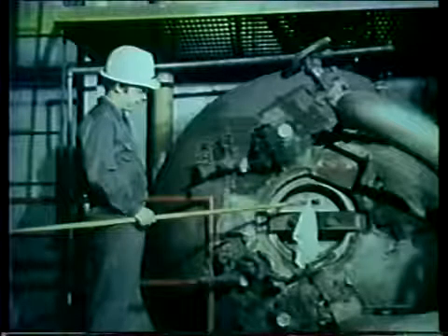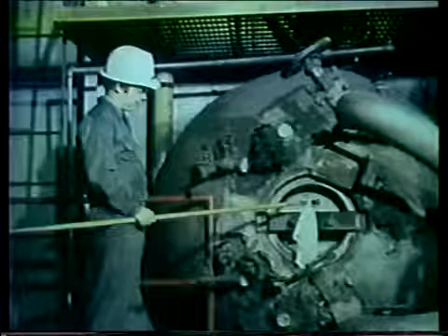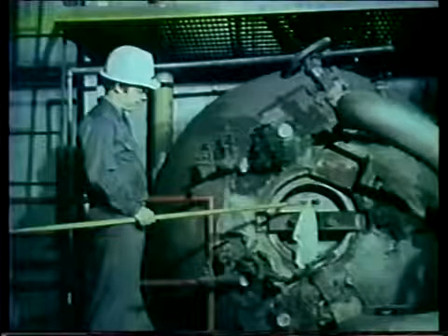Don't get too close to the covers until you know exactly what you need to do and where to do it. Another way to find a steam leak is to listen for it. There's a loud, high-pitched rushing noise associated with this kind of leak. Always listen for leaks when working around a pressurized boiler. Remember, each plant runs a bit differently. Always check your own plant's boiler manufacturer's manual and the safety manual.